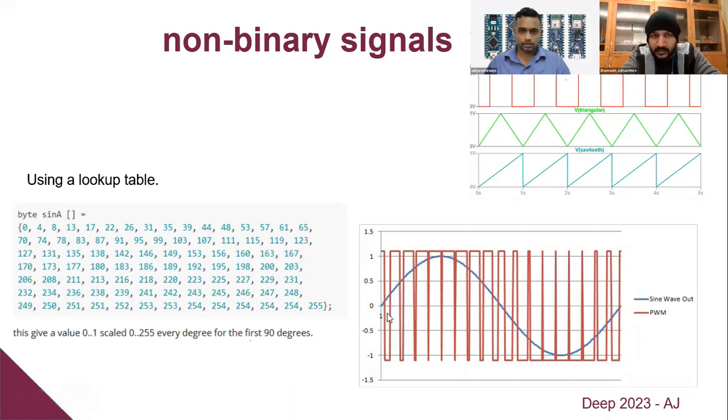So it will generate the sinusoidal waveform. The pin will be on and off according to this shape, right? Yes, exactly. Right now on this table, we are seeing what's happening from 0 to 90 degrees. In 90 degrees, we get from the middle point to the first maximum of the sinusoidal wave, which is 1, exactly what you're showing by the cursor.